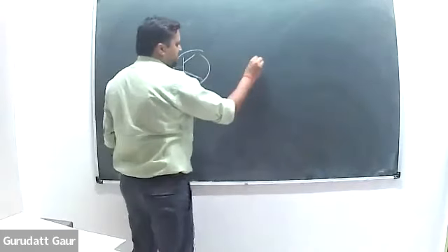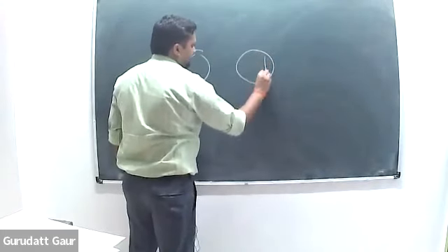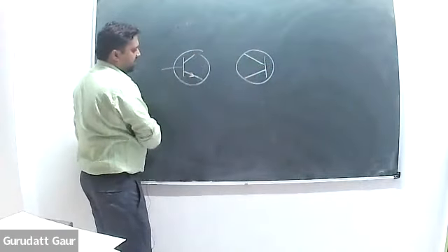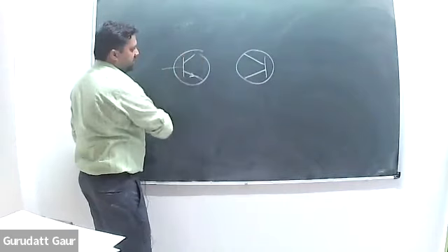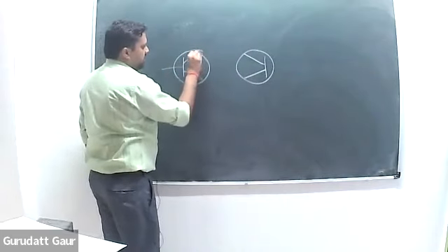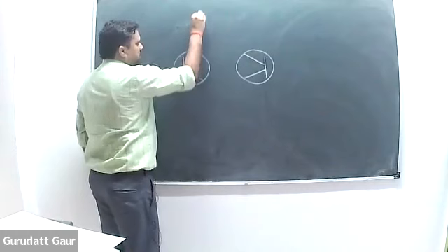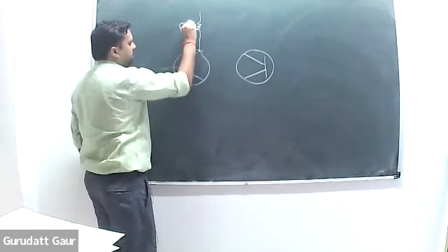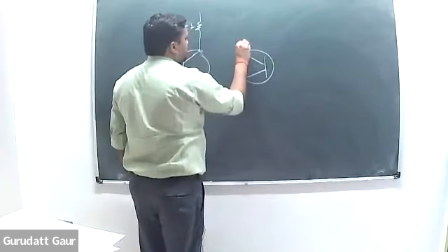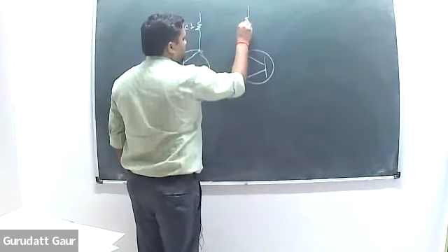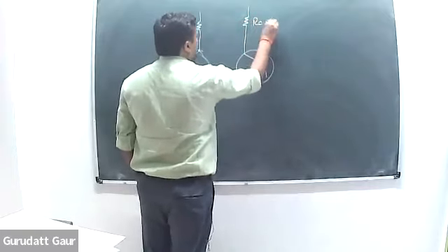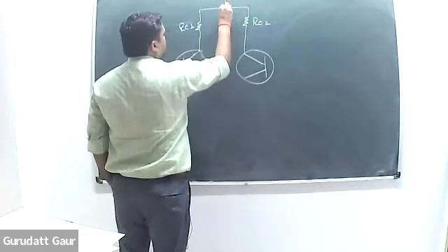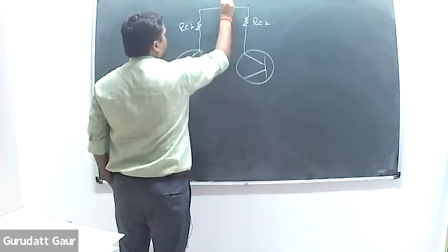Yeah, yesterday also I faced this dilemma. Let me see if I can do it nicely. So this is NPN. So this is the direction of current. This is emitter. This is base. This is collector. So this will be connected to some collector resistance. Let me call it RC1. This will be connected to another collector resistance. Let's say RC2. And of course, we need a VCC. So VCC for both could be the common.